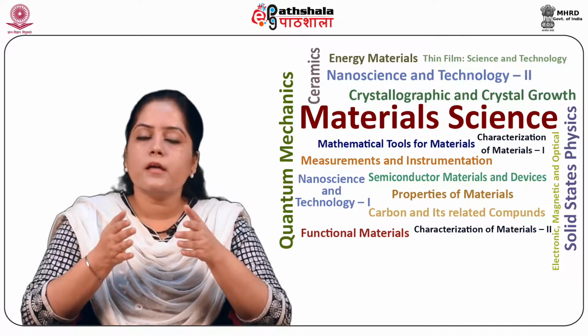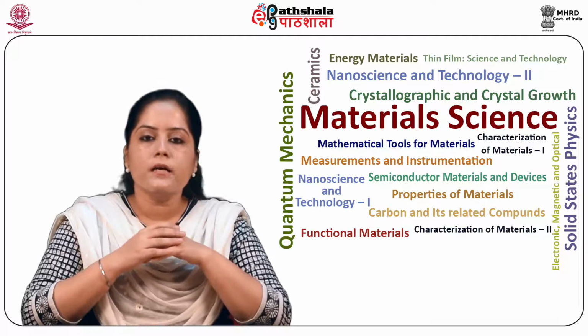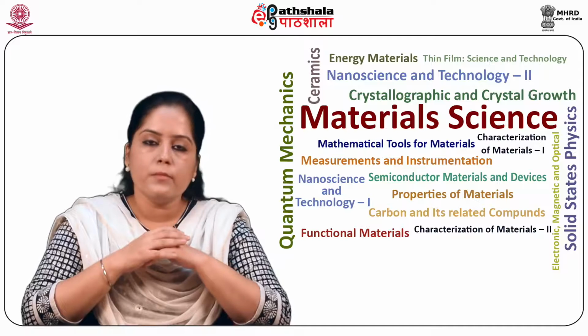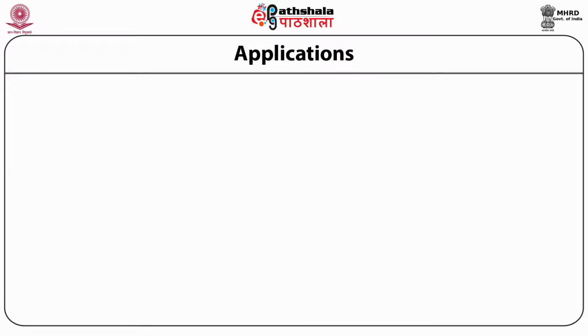Lastly, compared to MESFET, MODFET can tolerate higher gate bias due to the higher barrier of aluminium gallium arsenide. Let us now discuss the applications of MODFET.